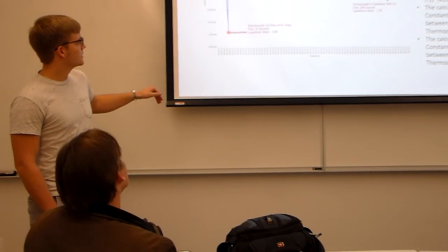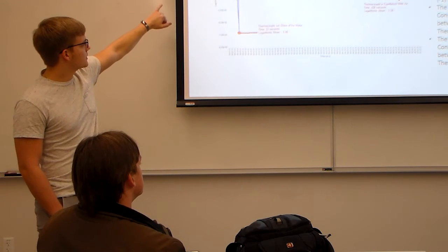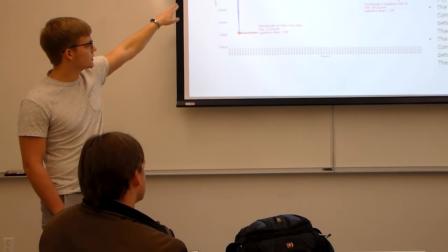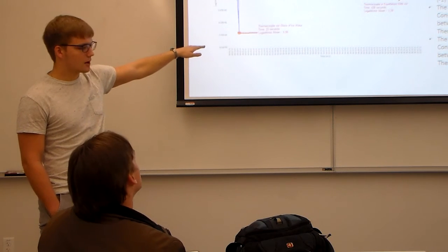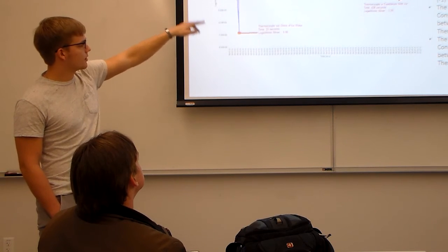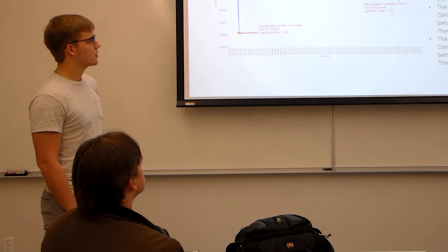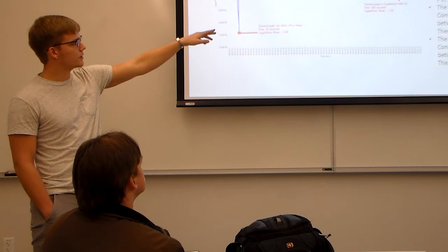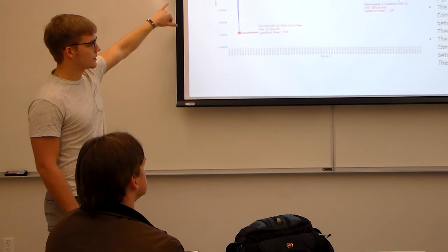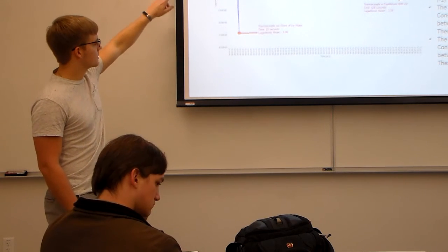And so here I did the same thing as on the previous chart, where I listed the boundary conditions. What's interesting here is that we don't exactly get a linear fit from entering the thermocouple into the glass of ice water and taking it out of the glass of ice water. It's more linear from the thermocouple in air to the thermocouple in equilibrium with the air. After we go through and do the math, which I showed over there, for the cooling of the thermocouple in the ice water we get that equation, which uses our boundary conditions from our change in time over the boundary conditions from our change in the logarithmic mean.